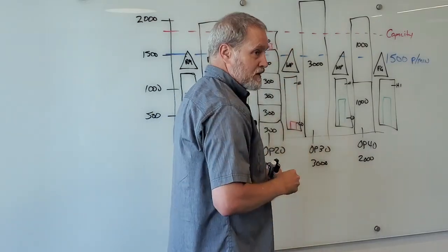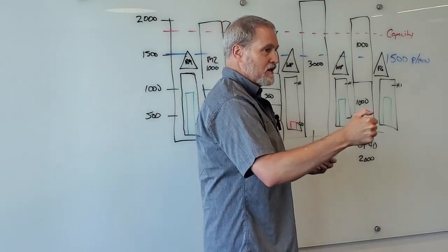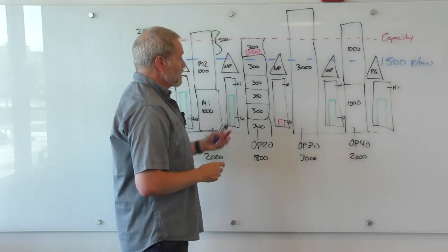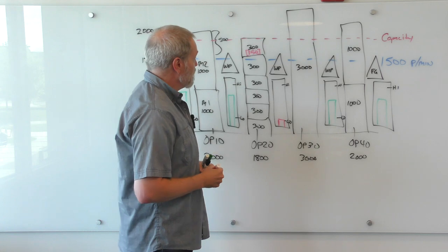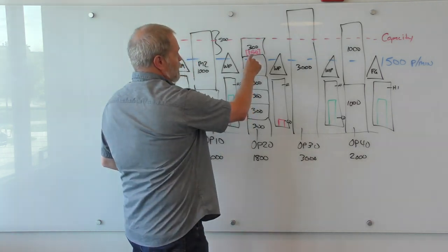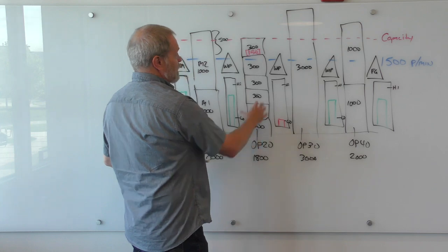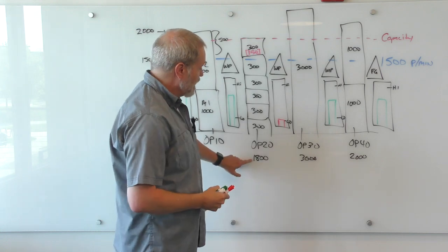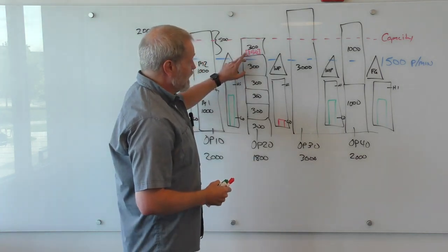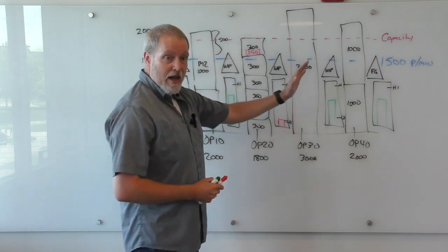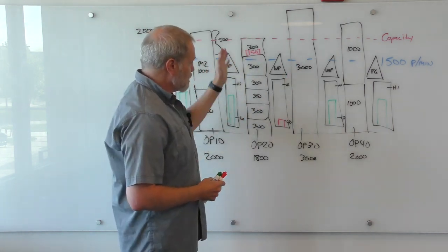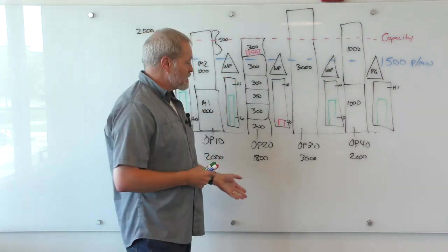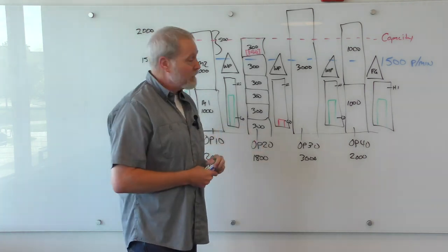And we could do this for various reasons. The operator adjusts the machine speed because he's dealing with a problem with jams on the conveyor or whatnot. You could also have one of these that was just down for unplanned downtime. But as that number drops, especially for your bottleneck, the capacity of your line goes down by that amount. So we've lost from 1,800, we've lost 150 on our capacity, and we cannot produce more than that throughout the shift. So focusing in on your bottleneck or your constraint in the line is a typical thing that people do. They manage to that, and they look upstream and downstream from that.